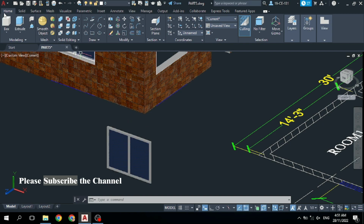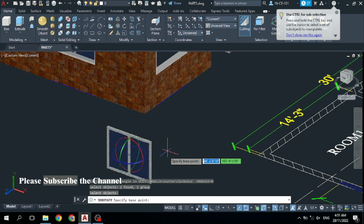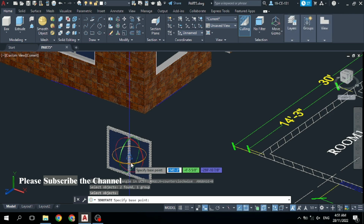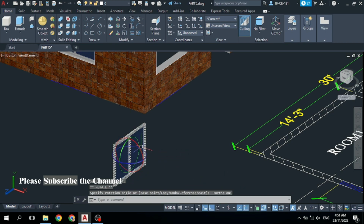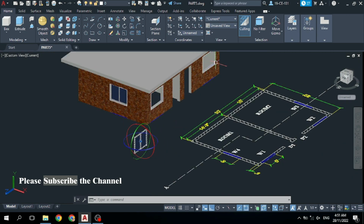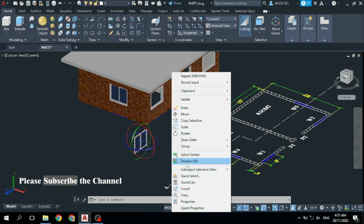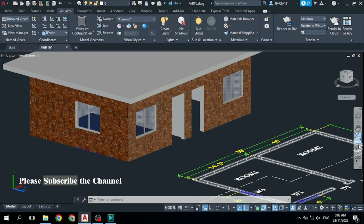For that click on home and click on this 3D rotate, and then select this object and press enter or right click, then specify this is your rotated direction. So ortho must be on. I want to rotate it by 90 degrees. Simply click here. Now you can see it is rotated by 90 degrees, and after that copy it to these two windows here and here. Now you can see these four windows are completed and seated here.